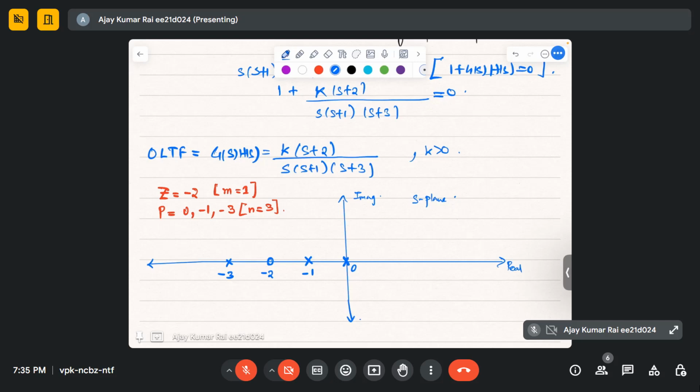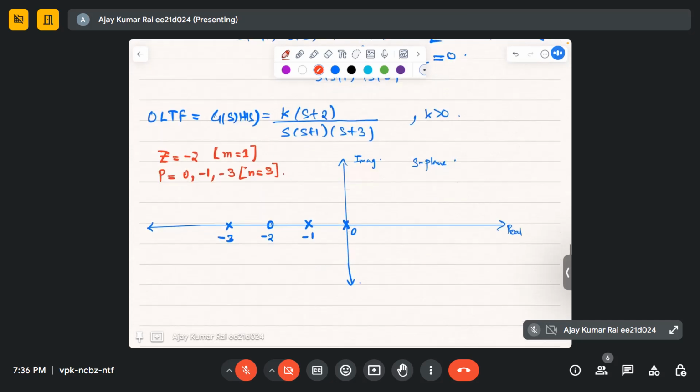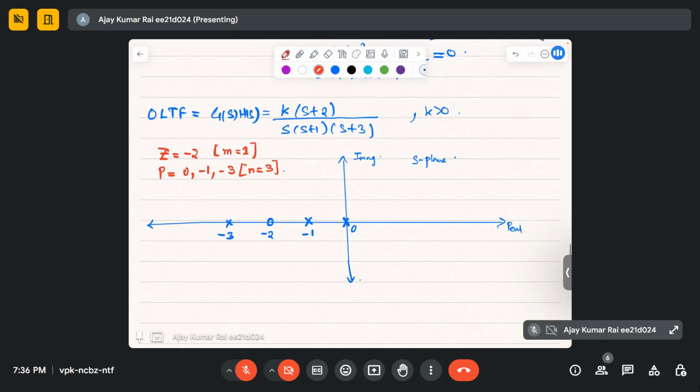The next step was to find the root locus on the negative real axis. Let's do what we used to do: choose some locations and see on the right hand side whether there is an odd number of open loop poles and zeros.